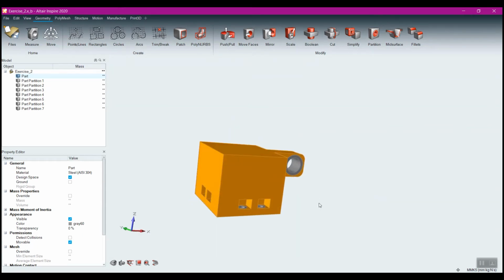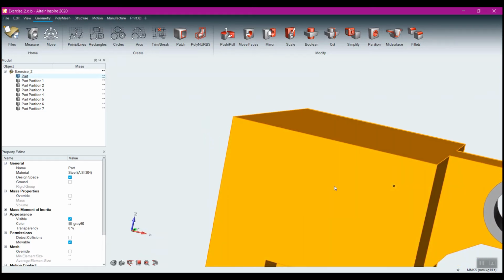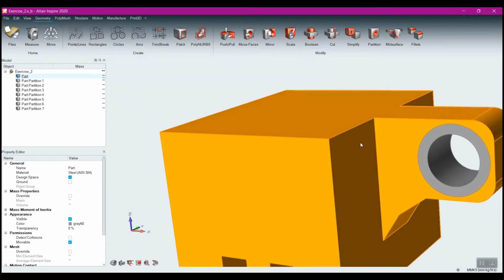So you could go a couple of different routes with the design space. You could create the design space in your CAD system. And remember that the idea here is to have a nice big blocky chunk of material. We're not going to put fillets on here. We're not going to clean it up. We're not going to make it pretty. We're not going to refine it. We want this nice big block of material. The refining comes after we do the optimization.